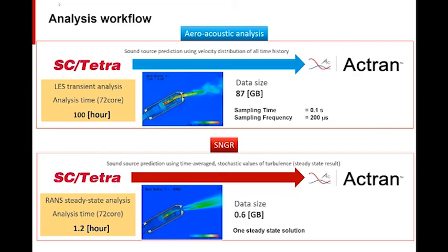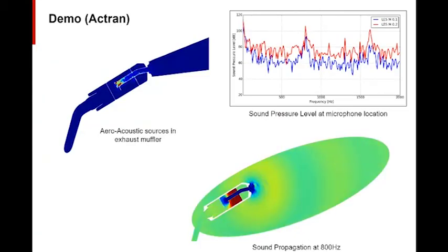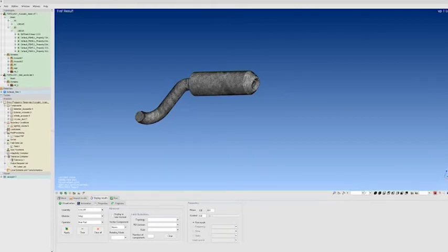So looking at the analysis, it's quite small I guess, but here is a direct frequency response analysis. So we will solve the problem frequency per frequency from 100 Hz to 2000 Hz with a step of 10 Hz. And you can see that this analysis is fairly simple. There are 4 components and 1 boundary condition. The first component we are looking at is this duct here, which is basically the inlet of our system. And what is interesting to note here is that we have a propagating mode -1, which is free. This means that every acoustic wave that comes across this surface in the direction leaving the system will not be reflected, will be allowed to just disappear at this boundary.